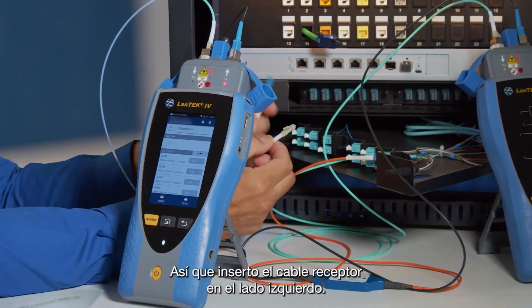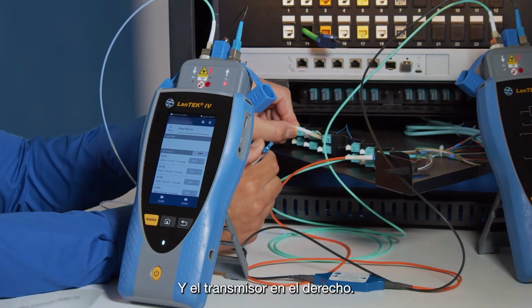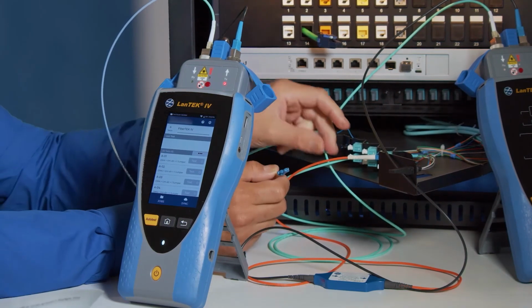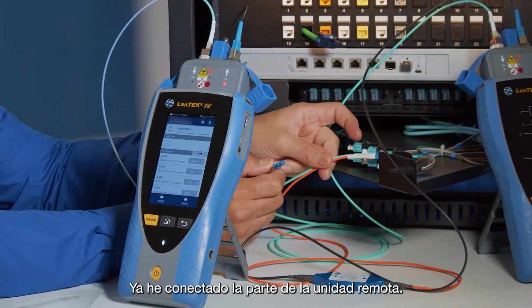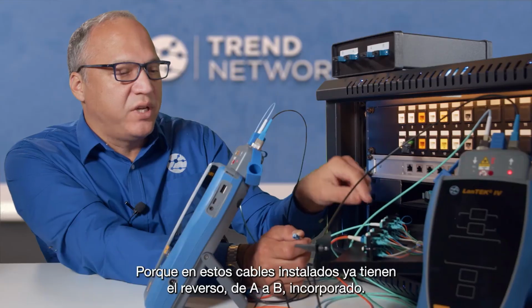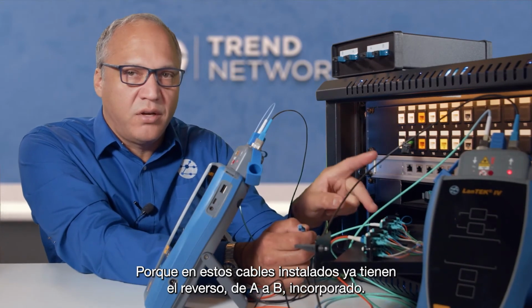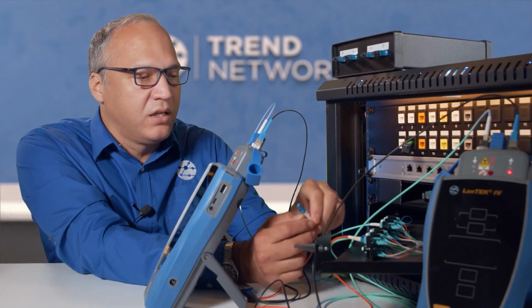So I'll insert the receive cable on the left and the transmit cable on the right. I already have the remote side hooked up here. Same orientation, receive on the left, transmit on the right. And that's because the installed cabling has the flip, the reverse from A to B, already in it.